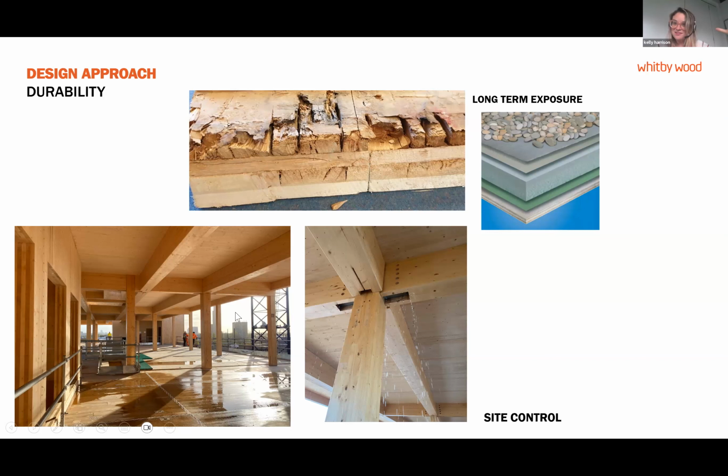And then once the cladding's up and everything's watertight, you have moisture sensor tests to make sure it's at the right moisture content, and then the building can start to be used. Now I've got a picture here of where you also need to really think about those connections, like I mentioned earlier, because on site, if it's exposed to water and there's a nice spot where water can get in and sit and leak through, and if it gets stuck inside a steel plate and then it's in your connection and you're rotting all of the wood around your dowels or bolts or screws, then that connection is going to lose its strength extremely quickly.